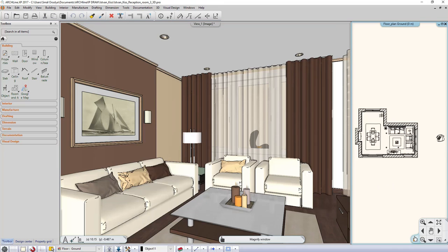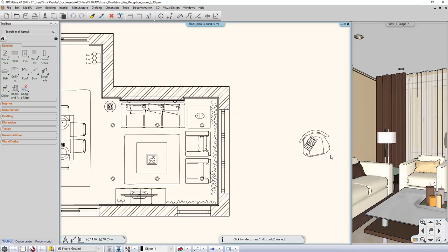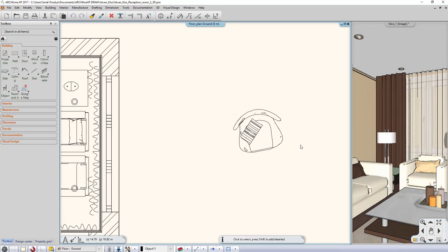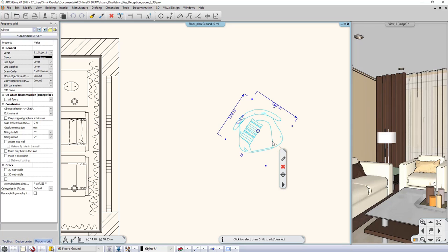Let's see how 3D shapes can be created. When we download a compound project, we may need to discard the unwanted parts. For example, we can remove the cushion from the armchair and then save the chair only into the library. You can do this by clicking on the object, so this will be displayed only in the 3D window.